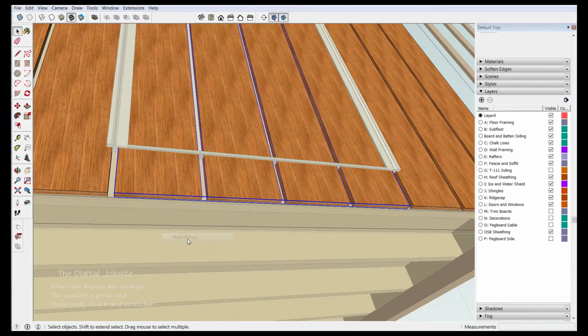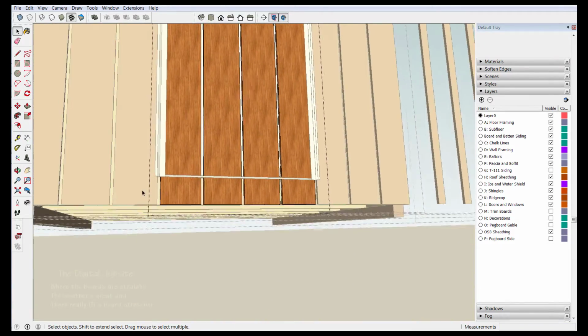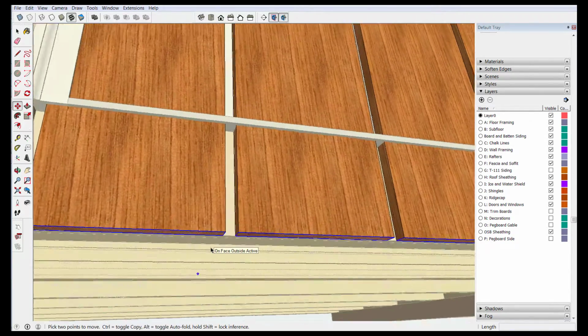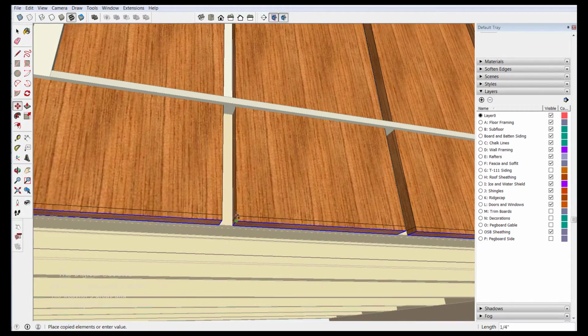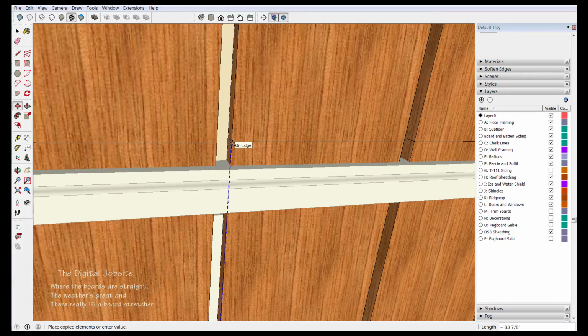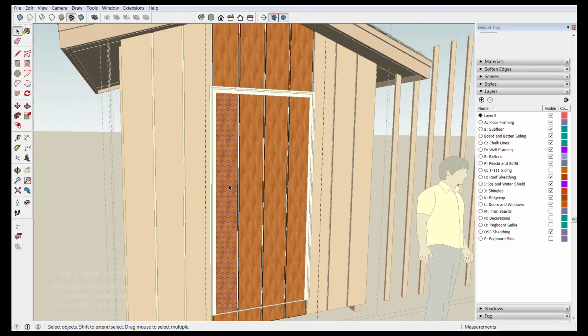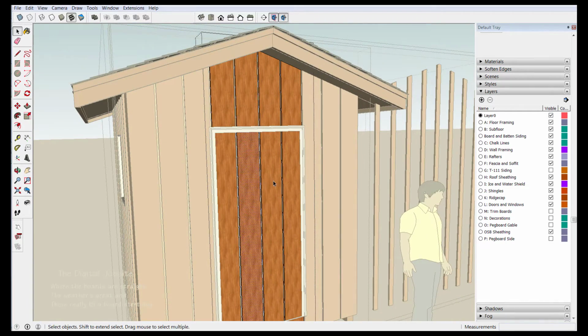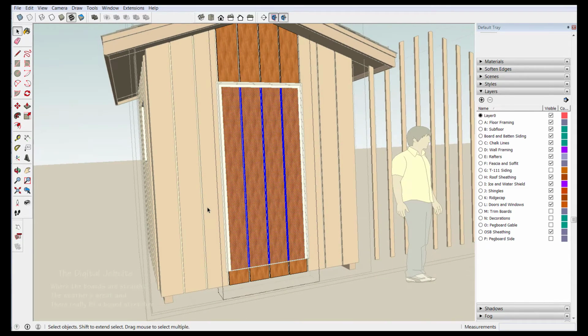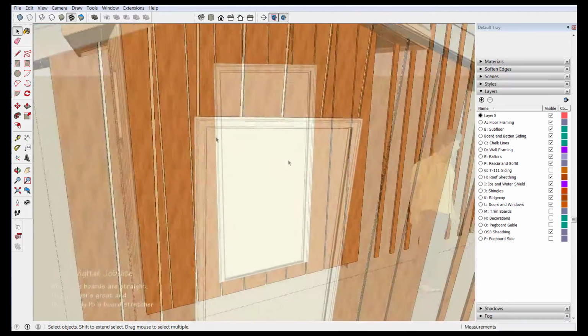Now I'll right click and make that a group. And by going into that group, now you can see we've isolated the geometry we're working on. Draw a box around the bottom with the move tool and the control key, and take one of these bottom edges by a corner, slide it up in the blue direction and park it at the bottom of the door. Hit move and control again. Slide these up carefully in the blue direction. Hold down the shift and index it to the top of the door. And you can tell if you did the steps right because these faces will be separated top and bottom. So with that done properly, we can just select everything in the middle and delete it, which gives us boards trimmed to fit around the door.